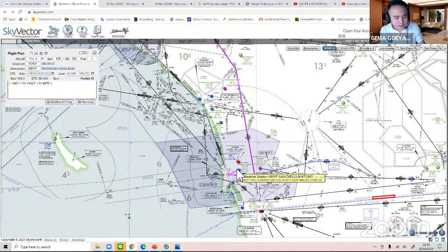If you are under Part 91, just a leisure flight or flight training, you can always delay your departure, unless you fly with a flight instructor and your mission is instrument training. That would be a great moment to get actual instrument flight inside the cloud. But other than that, you have to delay it and see what happens in the next hour or 2 hours. I believe the weather will clear up.